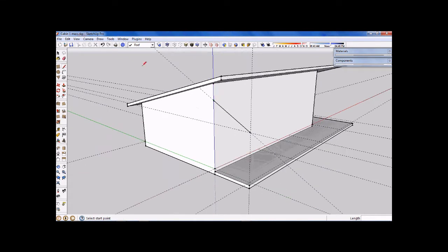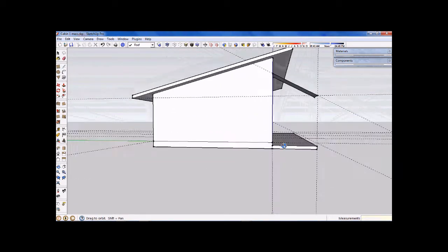and it really doesn't even matter how far you draw this back at the moment, but just come from this end point and come back on red axis, or on face, but as long as you see the red axis there would be fine, and set some known distance up. Like we might even work with just 1 meter at the moment. So 1000. I think I might just escape at that at the moment, so I can come down to this other end point, go back also in red axis direction, exactly 1000 again, and then I might close that surface. So by doing that, I've created a plane 1 meter deep just for starters,